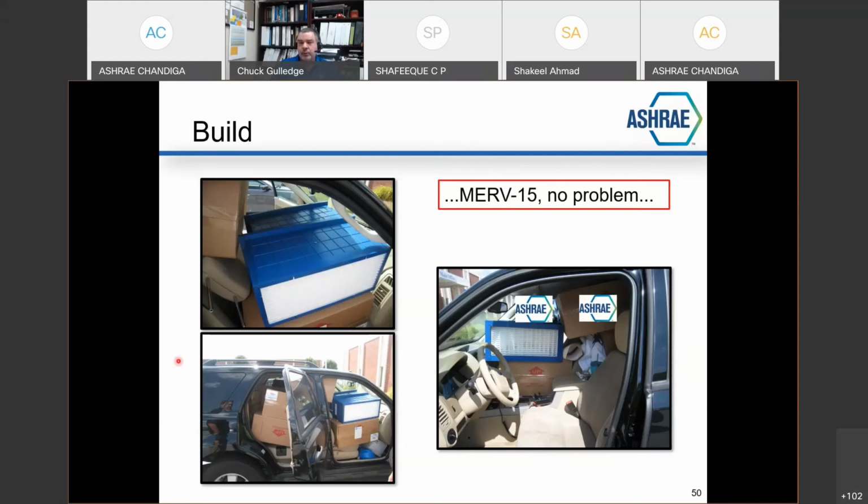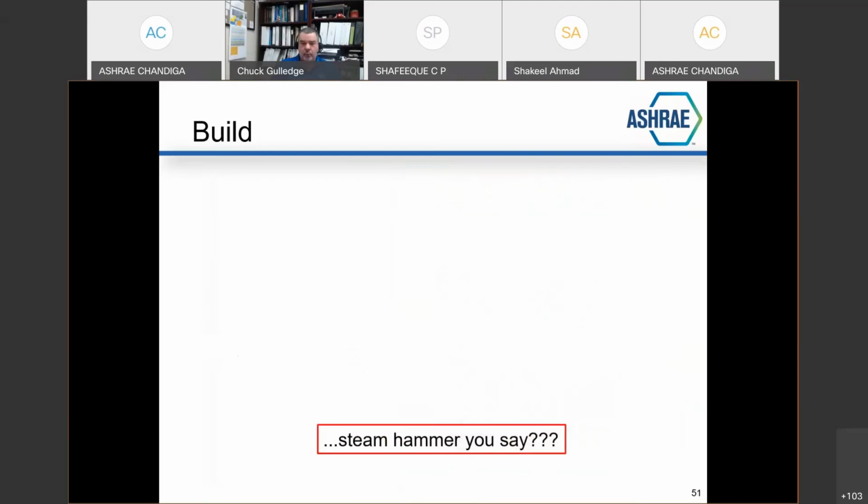Pay attention to availability on what you're trying to do with filtration, especially in these days of COVID response, where ASHRAE is suggesting that you start looking at minimum MERV 13 and 14 filtration instead of MERV 7 and MERV 8. Availability, understanding availability is important.